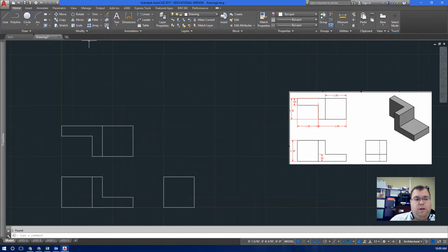The last command we're going to use is offset once more. For this one, we're going to type 0.5. Choose the bottom line and go to the top, and then the line on the right and go to the left. That last line we just did, we're going to select. We'll come to Drawing, and we're going to turn it into a hidden line. And with that, this shape is completely finished.